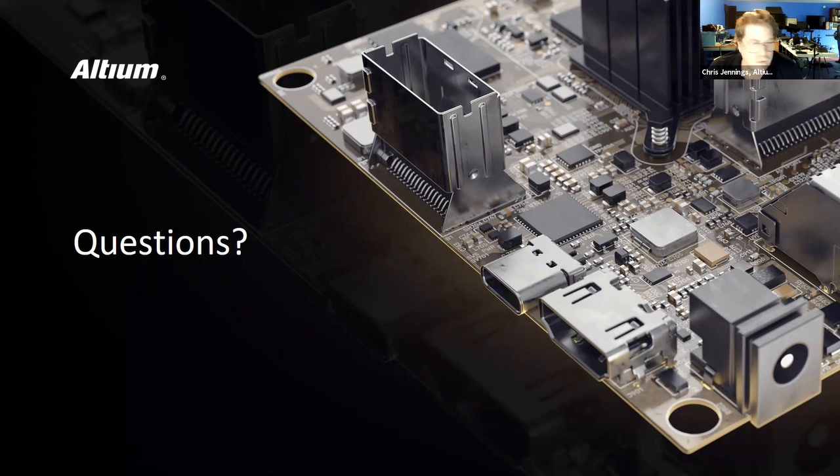I mean, the other thing that occurred to me is I would probably, and maybe it's prohibitive to do, want to actually have a real live board for the vibration testing, because I personally would want to check to make sure the thing worked after the vibration testing. And if they're all dummy components, you're not going to know. You're going to know if they fly off the board or if there's damage to the traces and leads, but you're not going to know that the board electrically works if it's all dummy components. So I have not used dummy components ever. I'm not saying they don't get used. I just haven't used them.